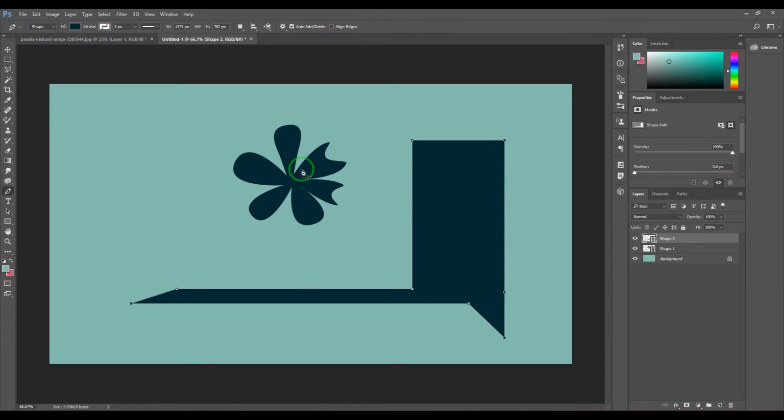Okay, now if I start adding one more shape, I want to subtract this. So if I want to draw that here, it's actually giving me a new shape layer. Instead, what I can do is come here and choose subtract from the shape and then click there, and then you have subtracted that. So this shape is minus that shape.